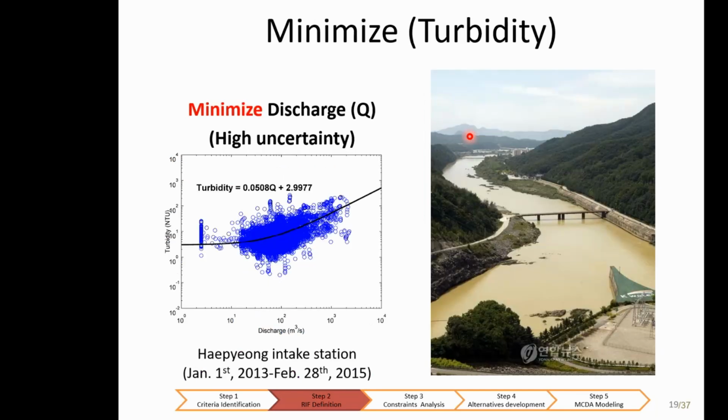So we're going to define constraints in our system. Turbidity has not been the big issue. I mean, it's still pretty high, between 1 and 100 NTU, nephelometric turbidity units, and you get a high variability. So it's very hard to connect this to discharge and whatnot. So the water is always a little bit milky or kind of a bit of a hot chocolate color out there.